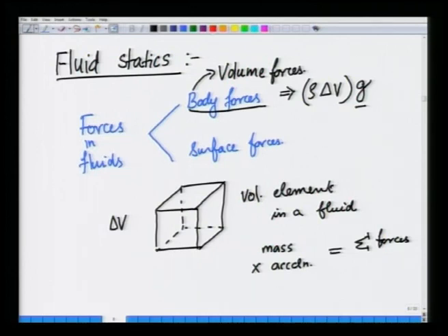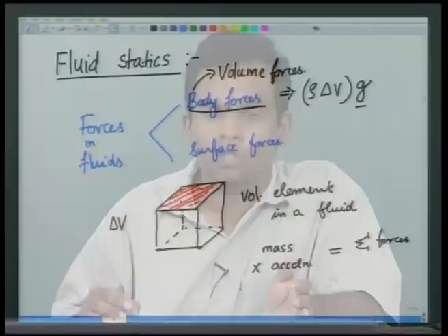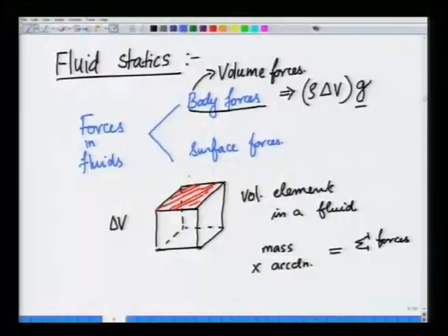In contrast, surface forces are forces that act only on the surfaces. For example, if you consider the top surface of this cubic volume element, the fluid that is present immediately outside will exert a force on this surface, and this is called a surface force. The nature of the surface force is ultimately due to molecular interactions.